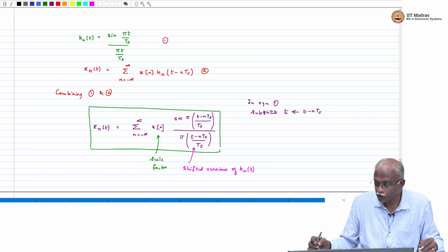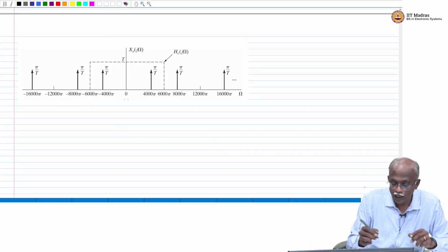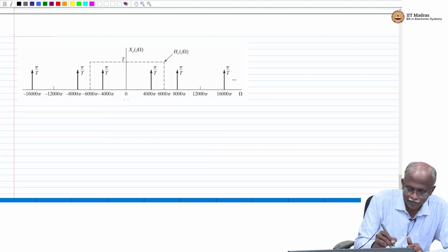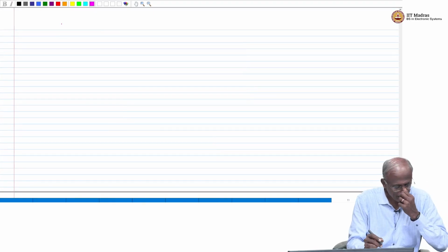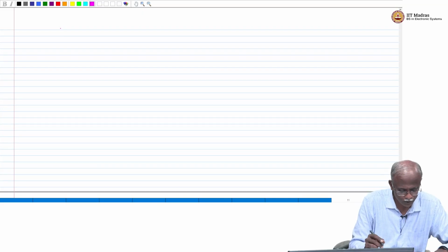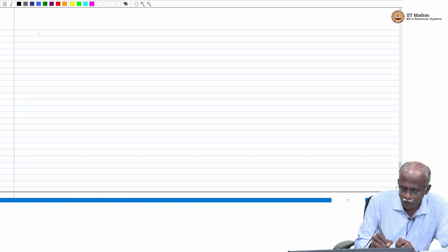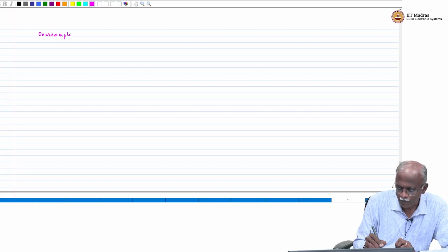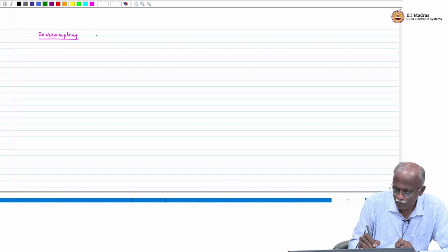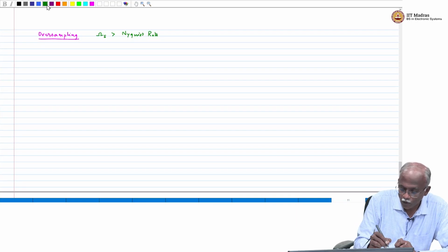Let me also address the issue of oversampling the signal. That means sampling at a rate higher than what you need to. By oversampling, I mean omega s is greater than the Nyquist rate. Now notice that when omega s is equal to the Nyquist rate,